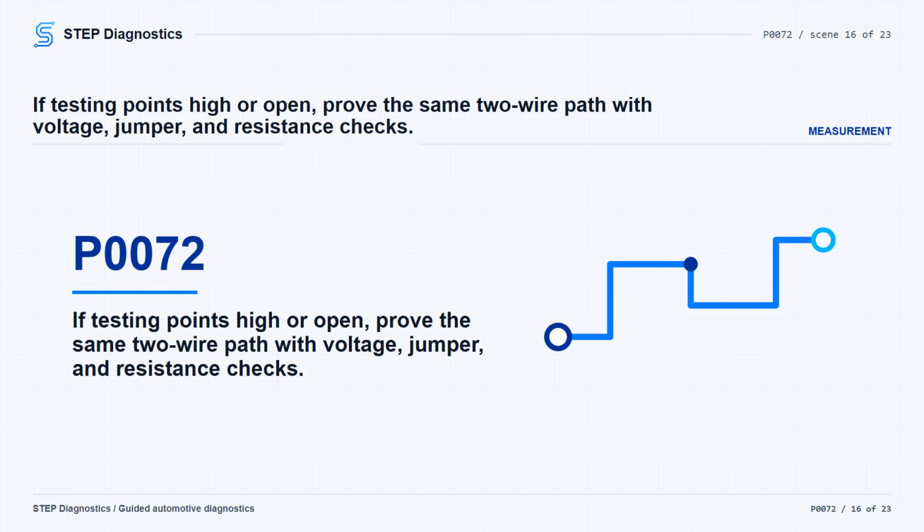With an active fault, monitor the scan tool and connect a jumper across the terminals with the ignition on. Typically, the temperature sensor signal voltage should change to 0 volts on the scan tool with the jumper in place. If voltage data is not available, watch for the circuit low fault to set with the jumper in place. Then check resistance of the temperature sensor signal circuit and temperature sensor ground circuit. Typically, the circuit resistance should be less than 5.0 ohms.